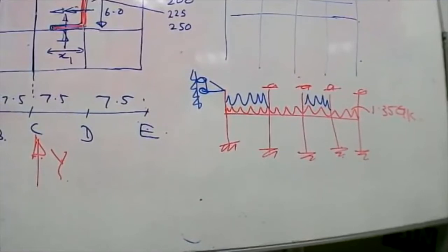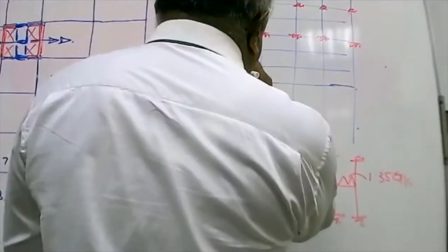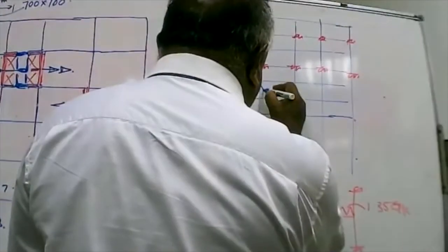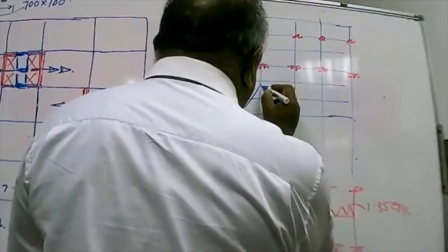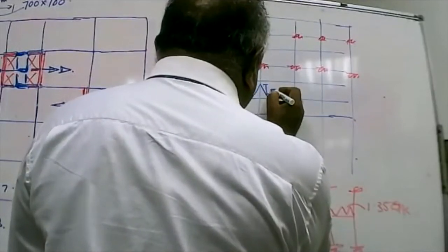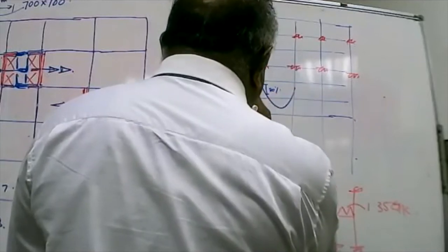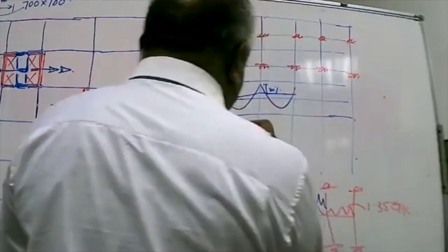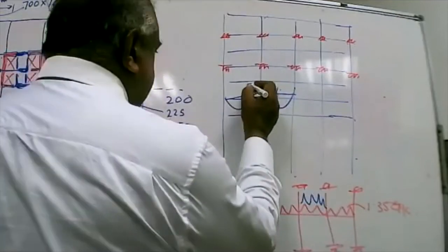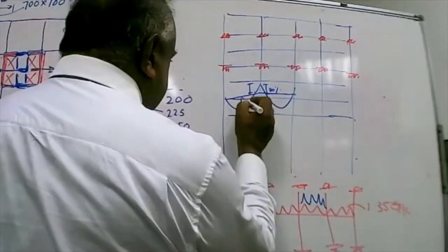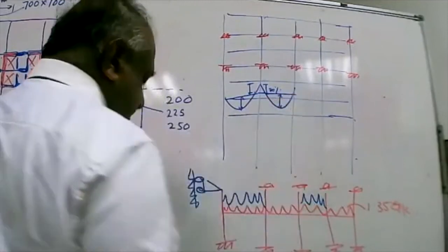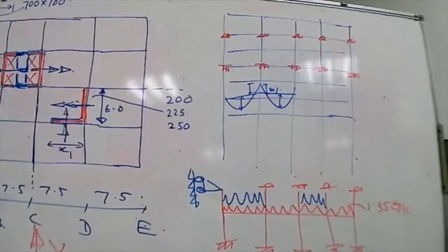When creating the bending moment envelope, you can consider redistribution of moments. If you get a bending moment diagram like this, you can say only 80% of the moment will act here. So you change the origin of the bending moment diagram line.